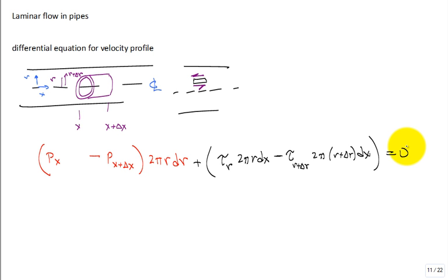Yes, sir. So where is the second pressure coming from if you have one flow going? It's right here pushing back. Where is that coming from? That's because the pressure is dropping as I go down the length of the pipe. In a real pipe that has viscosity, the viscous shearing will have a pressure drop as I go down the pipe. And that's what gives us the velocity profile, no slip at the boundary, and then at the center you have that maximum speed.